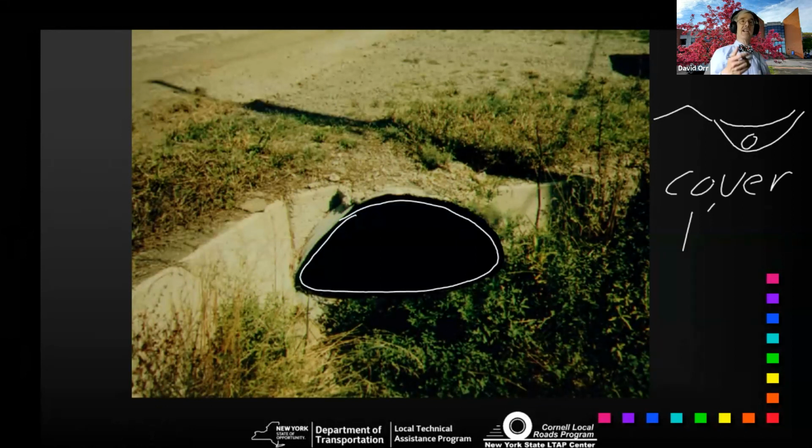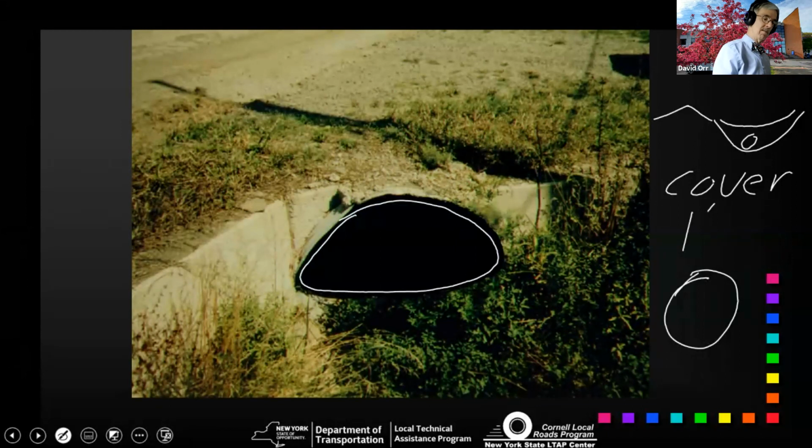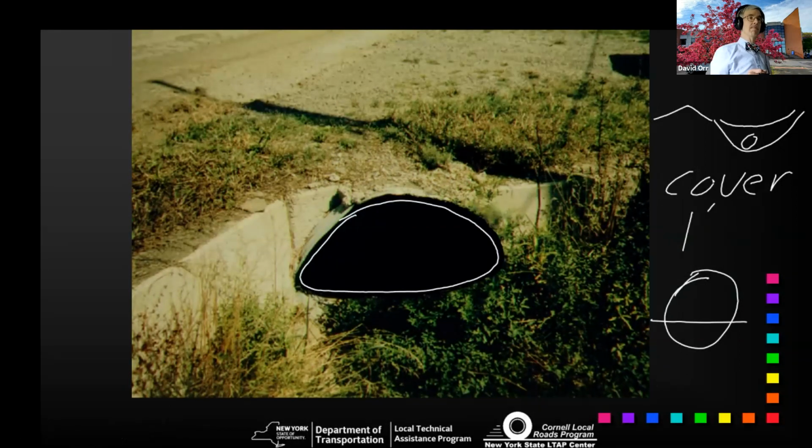If not, then I've got to think about either putting in a different shape, or you could even bury the pipe. People sometimes do that, and they bury the pipe a little bit. But remember, if you do that, the pipe area is reduced because it's the area between the pipe and above the streamline that you've got to calculate. Now, the Army Corps actually likes that. It's good environmentally. There's lots of reasons, bank to bank, that kind of stuff you may have heard about. But remember, it's the area.